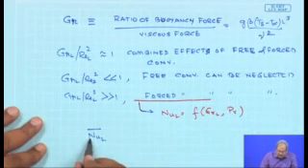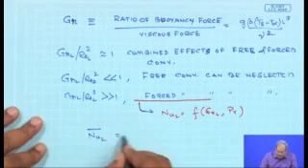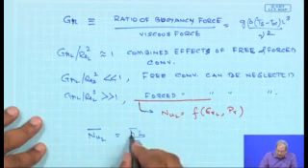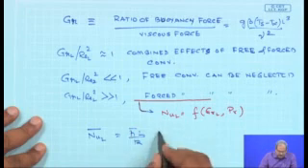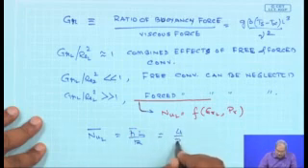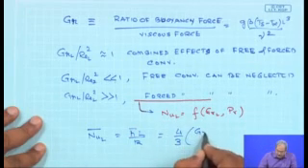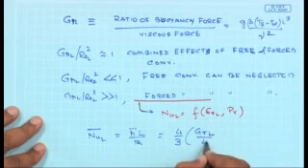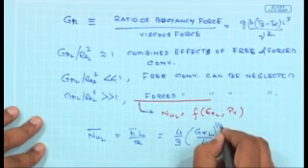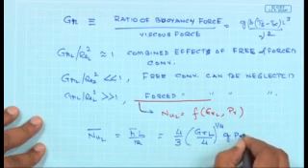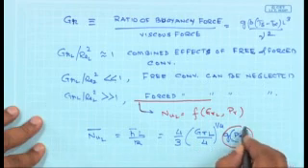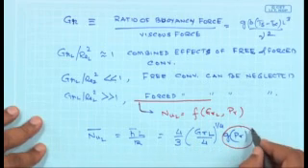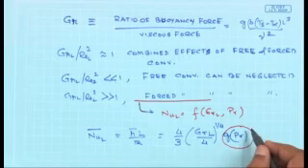For example, the average Nusselt number in natural convection, h bar L by k, where h bar is the average heat transfer coefficient for free convection, is given as 4/3 times (Grashof number based on the length by 4) to the power 1/4 times g(Pr). This g(Pr) is a function of Prandtl number, the values of which are provided in the text.